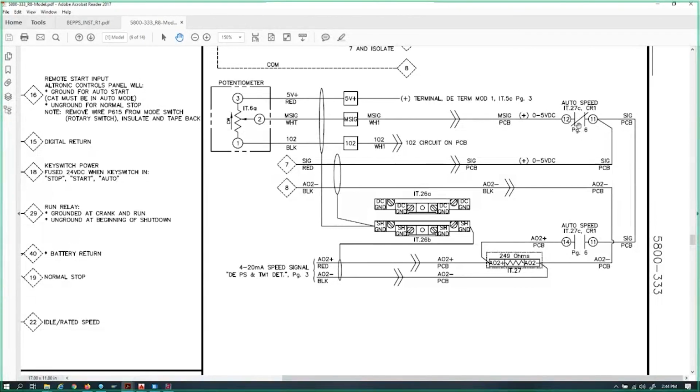It returns out through a normally closed contact on our common contact, terminal 1, and we say, hey, hook this signal from the PCB back up. Now it enters a wiring harness back into Cat terminal 7 where we told you to disconnect it earlier up at the top. So all we're doing is using our potentiometer, which is much less expensive than Cat's should it fail, and we're substituting it in. That's it, plain and simple.